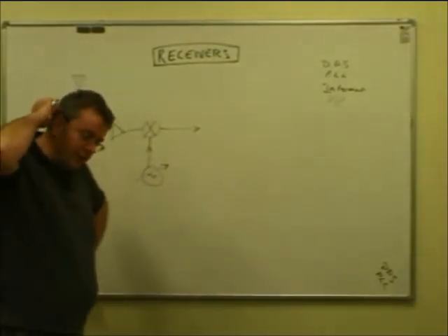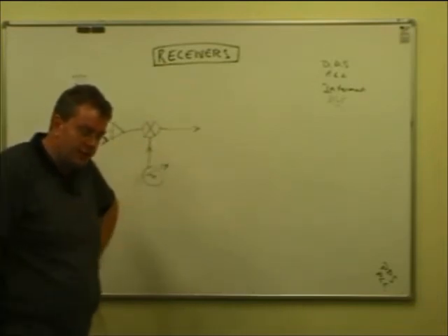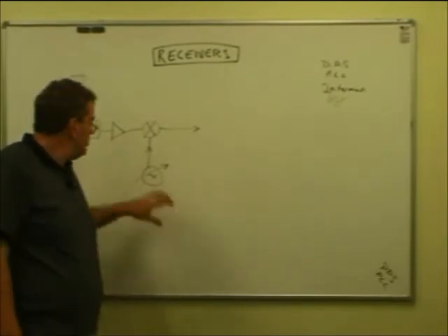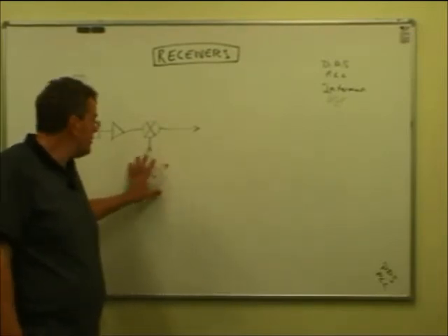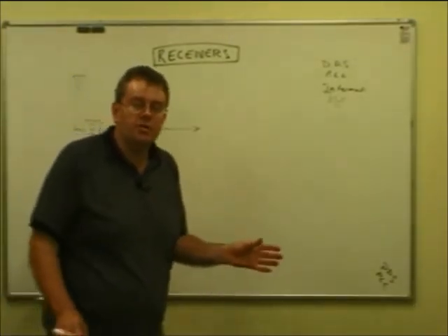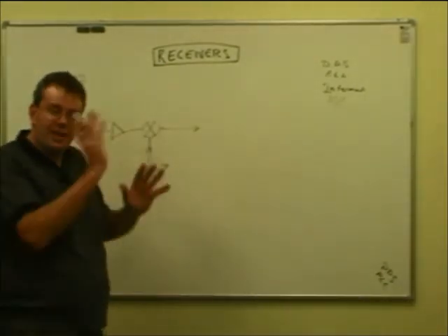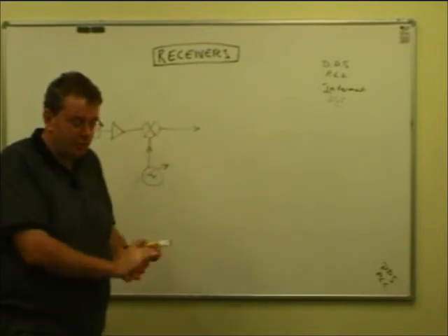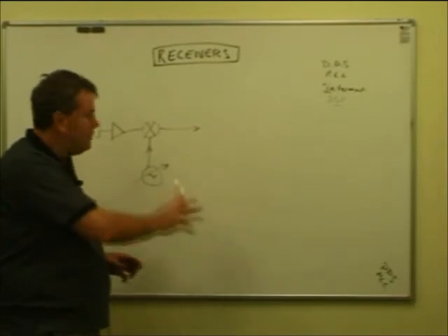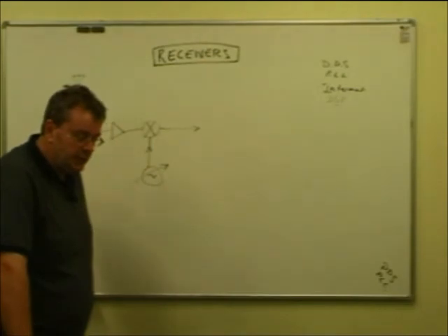And you had an arrangement where the tuning knob on your set was connected to some digital electronics which would take a sniff of that free running oscillator signal, compare it to a fixed crystal oscillator reference, and then put an error signal back to the oscillator to keep it locked onto the frequency you wanted. It was called a phase lock loop. So it was comparing the oscillator to a reference according to the setting of the knob and keeping the local oscillator on frequency.